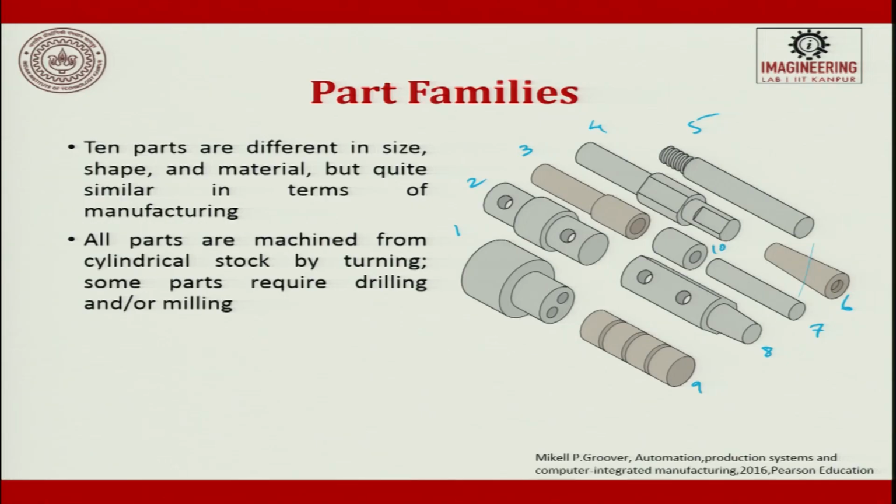So, now for doing all these parts, what you need is a machine, minimum a lathe machine. Then in the lathe machine, you can try to have holes made, grooves made, taper made, right. So, all these things can be made in a shaft. If you want to make a completely drilled hole, then after this lathe machine, you have to go to a drilling machine.